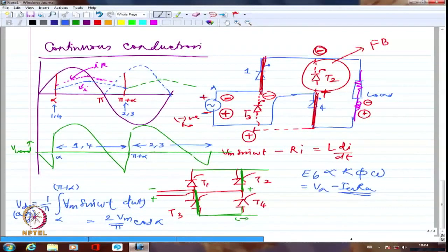So power electronics research is going towards increasing the rating of these rectifiers which charge the battery. So you want to push 300 amperes, 400 amperes of current in one go. Can we do that? Whether the battery will be able to withstand that, whether our rectifier will be able to deliver that much. So a lot of research is going on towards that particular area. So this is one of the applications of rectifier.